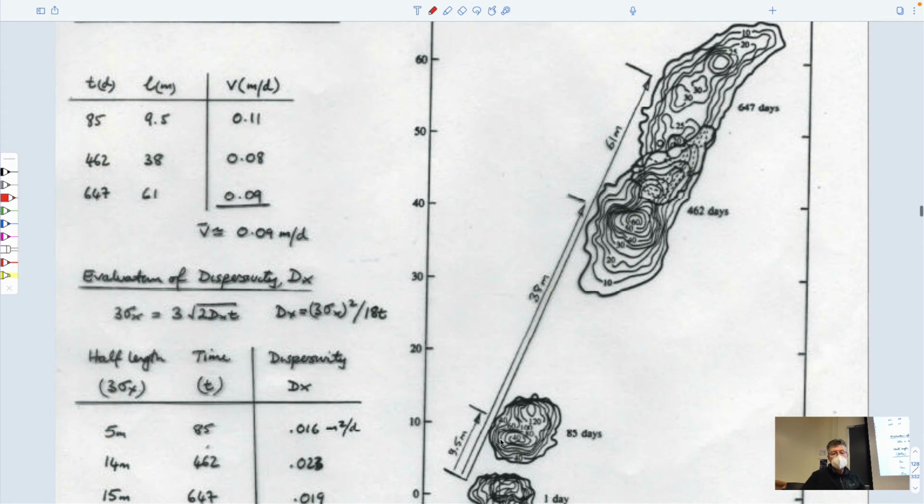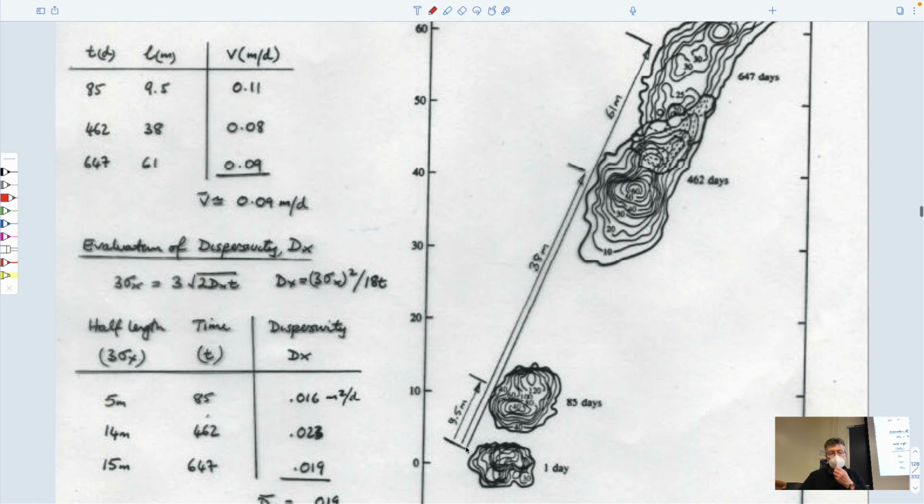This happened to be done at a site that wasn't contaminated, but was contaminated on purpose, on a Canadian Air Force base, Borden. And so a hole was dug, and sodium chloride, salt, was put in, and it was a very shallow aquifer that could be sampled by just pushing capillary tubes into the shallow aquifer a couple of feet and sucking a sample out. So you could get these very dense contour maps of the distribution and concentrations as the plume goes down gradient.